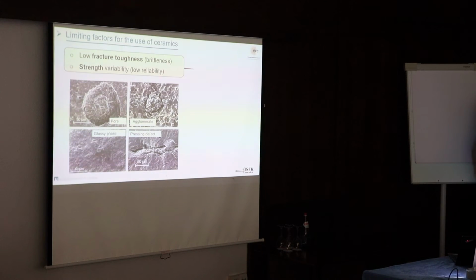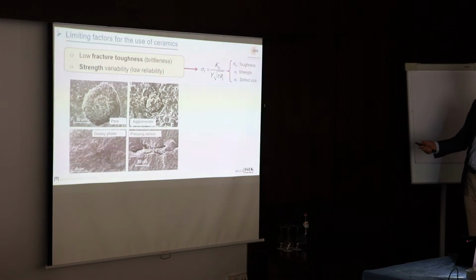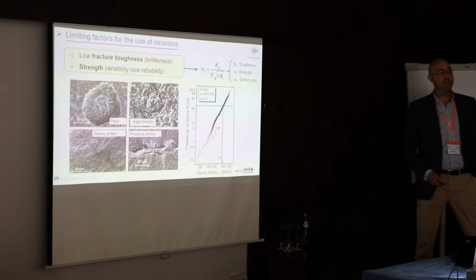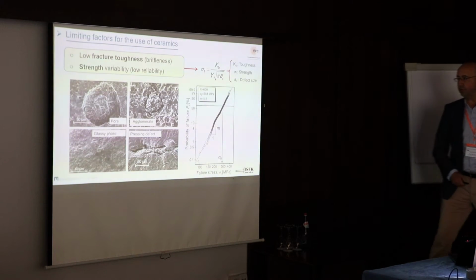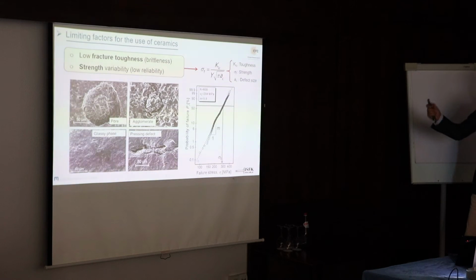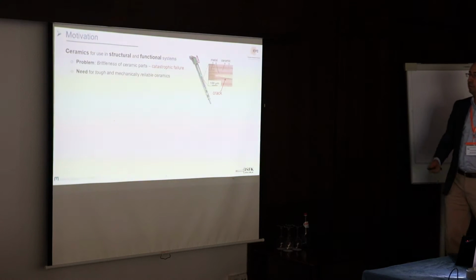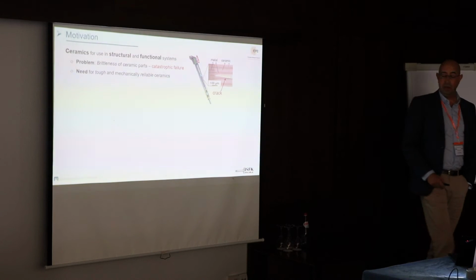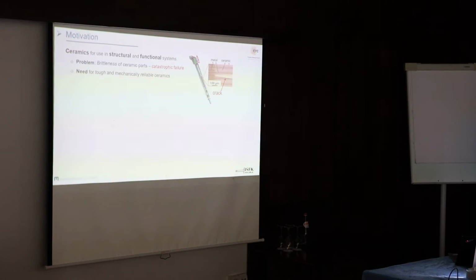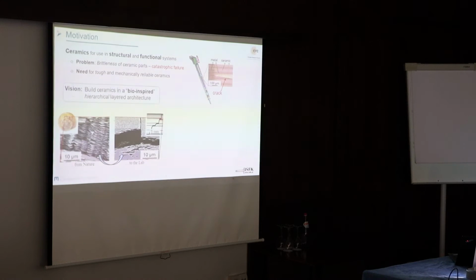We deal with defects in a way that we use inelastic fracture mechanics to describe failure of ceramic and brittle components. We have a probability of failure, and these are the two main parameters we have to deal with. So we have scattering strength, low reliability, etc. And that poses a challenge in terms of designing reliable components, where the initiation of cracks and their propagation impair the